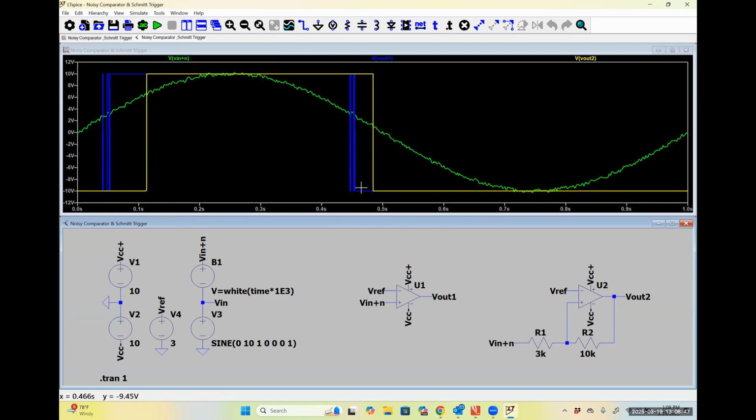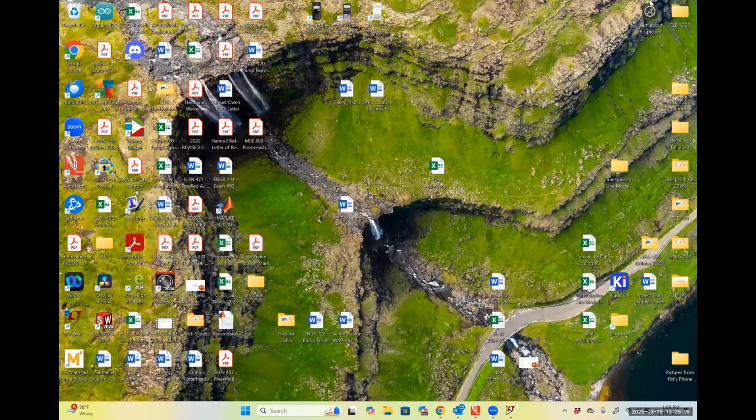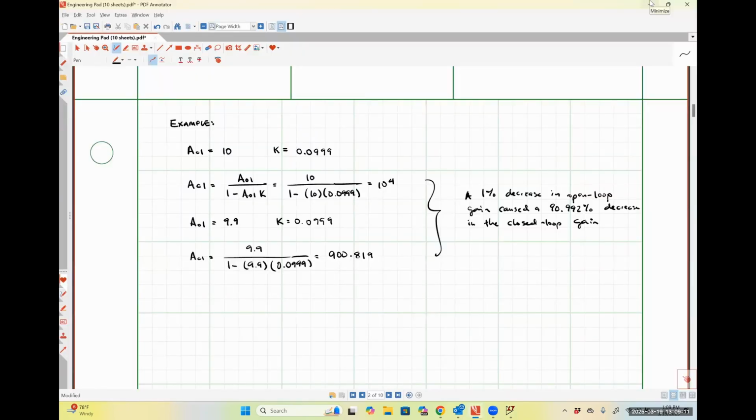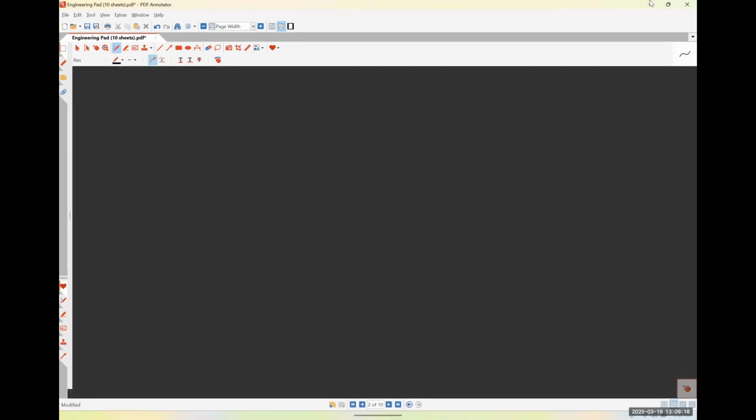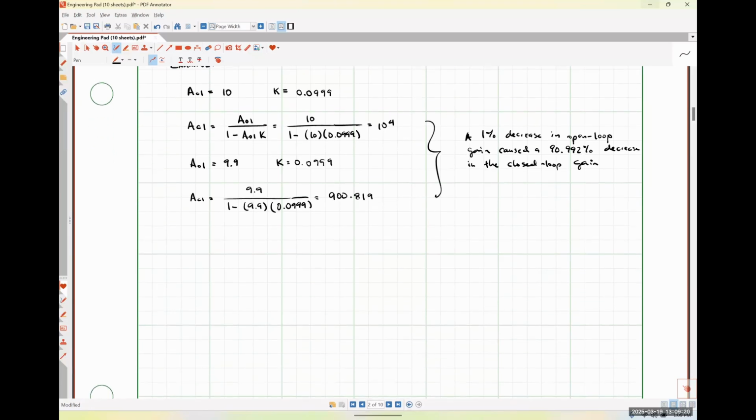So I want us to do a little bit of math and circuit analysis and see if we can figure out the relationship between what the values of those resistors are and where those transition points are going to happen. Okay. So the first circuit that we're going to look at is what's called the non-inverting Schmitt trigger. It's exactly the one that I had implemented in LTSpice. Okay.